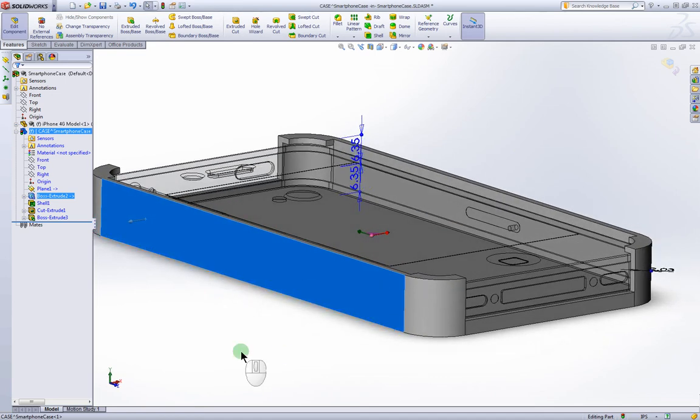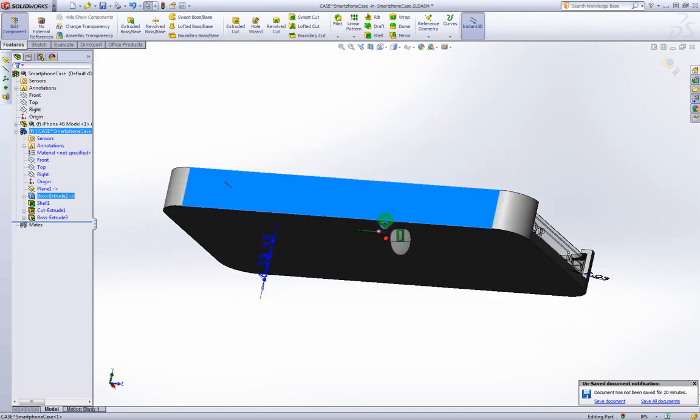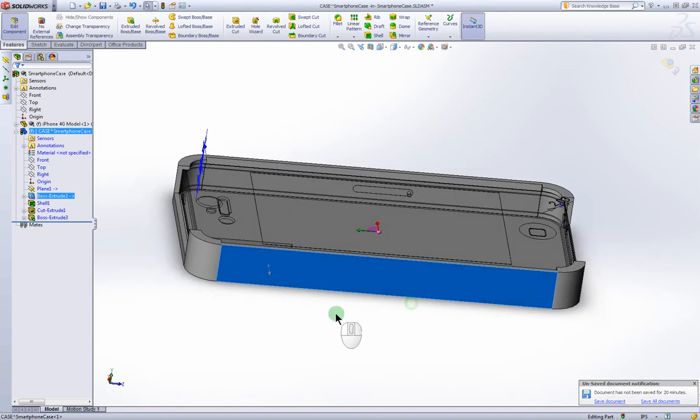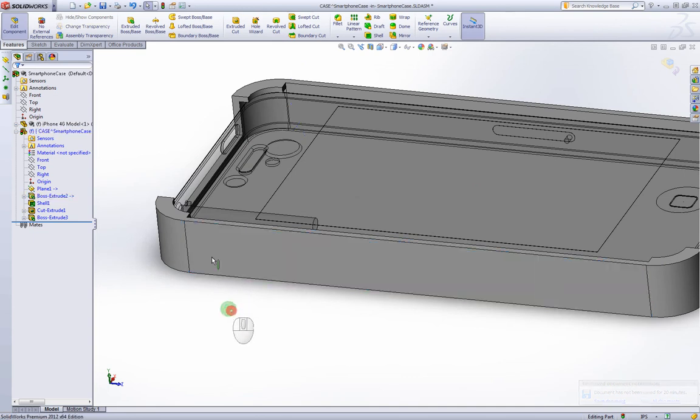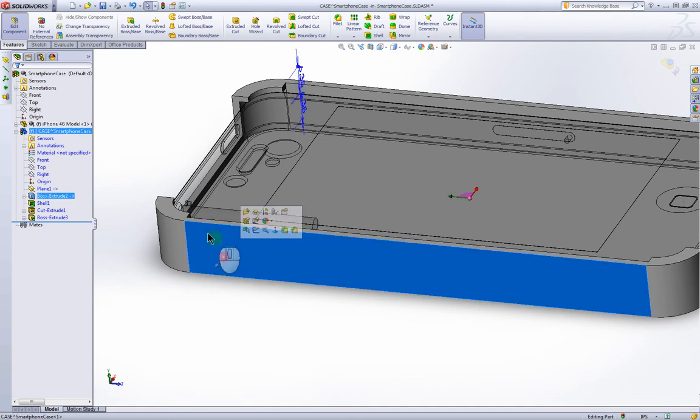Now before we leave, we're going to round all the corners with fillets to make it smooth so it's nice and feels good. And we're going to put a hole in the back for the camera. So we're not done. We're not out of the woods yet. So to make the volume holes, it's fairly straightforward. We're going to sketch on the side where the camera button, the volume buttons are located, and then we're going to cut the shape away where we want some material removed so we can actually touch these buttons.